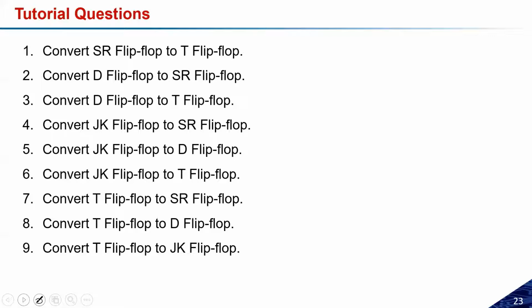While converting or designing these flip-flops, you need to keep 2 things in mind. If in the problem it is not given what kind of clock is there, you can use any one. Okay, so this is the first thing. Second, if it is given, then definitely you have to make the clock arrangement as per the problem statement. The second thing that you have to consider is, if in the problem it is not written that it should be hazard free, you can use a normal one. You don't need to use the redundant pair.